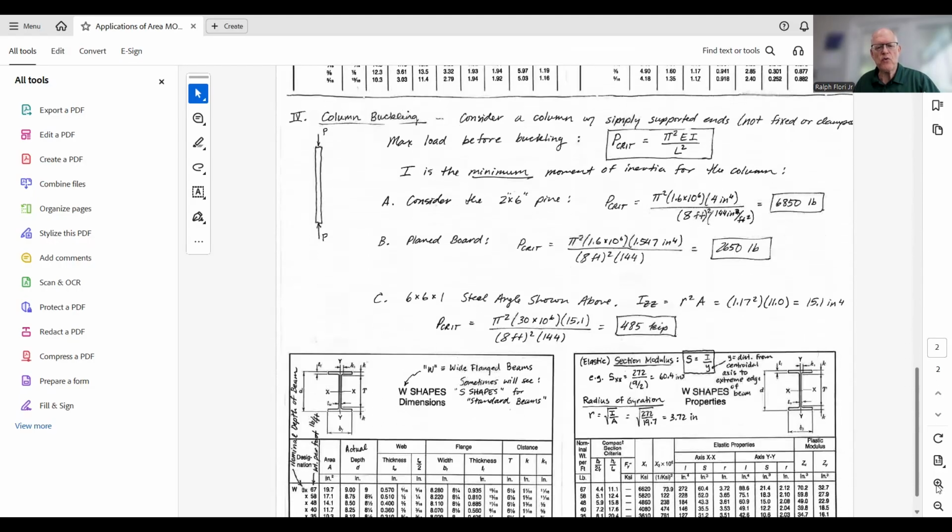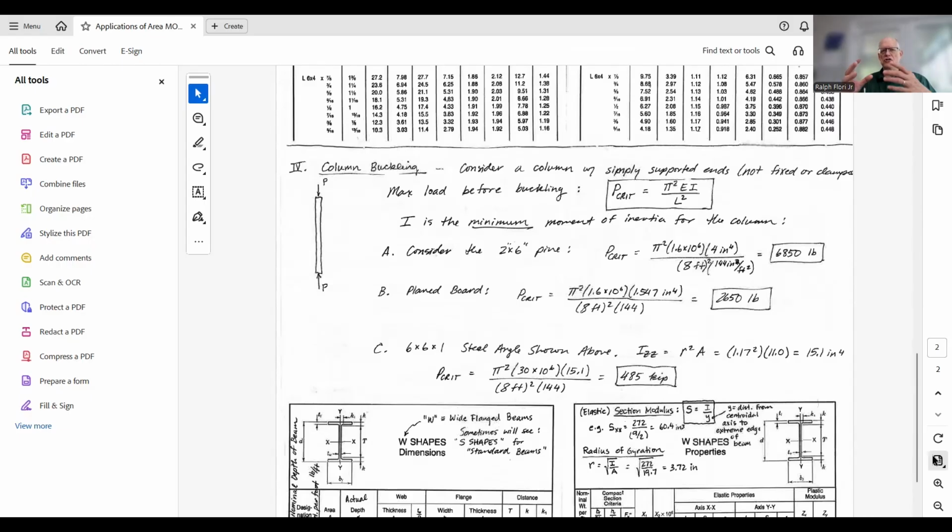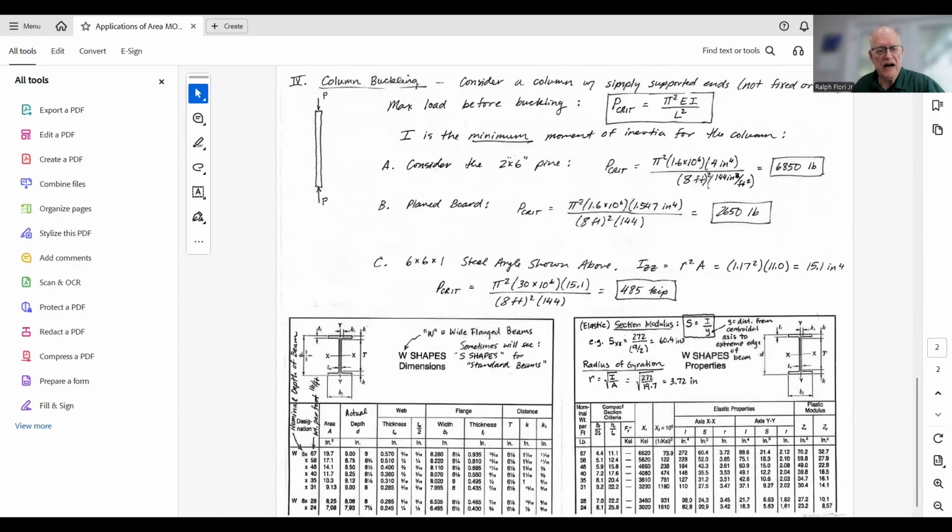One more interesting thing we're going to do in this chapter in statics is talk about how the area moment of inertia for a given area varies depending on the axis that you choose. About some axis across that area it's going to have a larger moment of inertia, and about another axis it's going to be smaller. For example, for this W beam, we saw that I was large about the x-axis and small about the y.